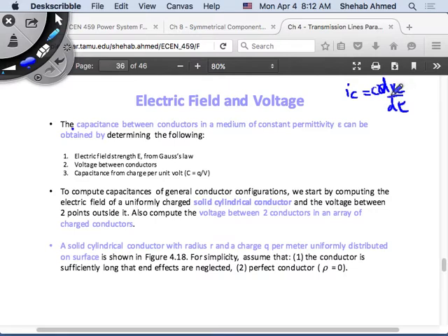So voltage across a capacitor and current through a capacitor are related by this first order differential equation. To calculate capacitance, which is what we need, I will bring dt to one side. So I end up having IC dt is equal to C dVc. If I integrate,